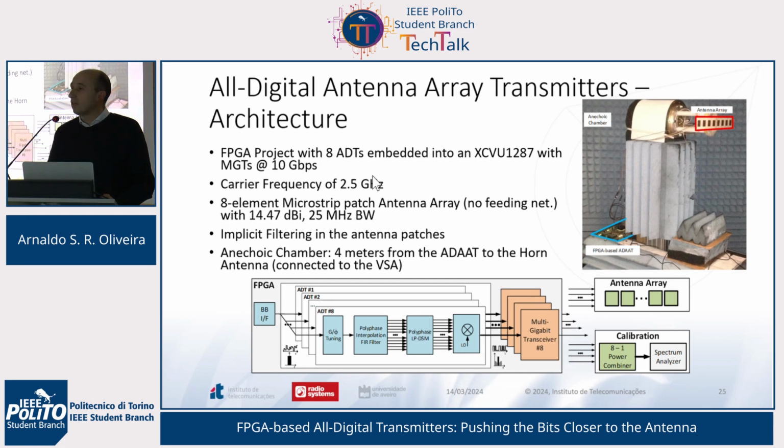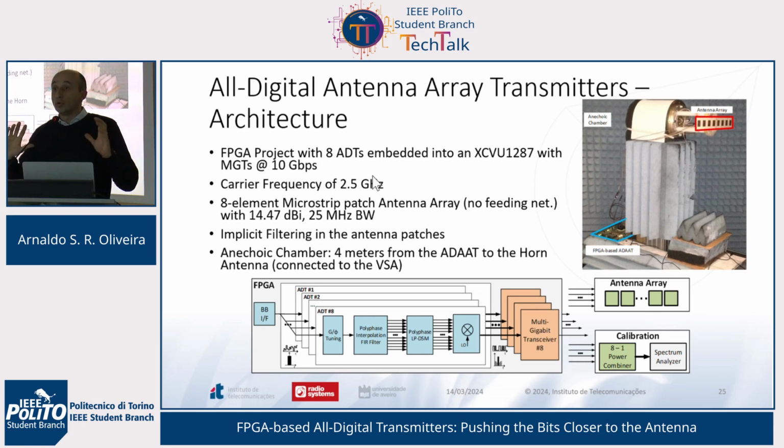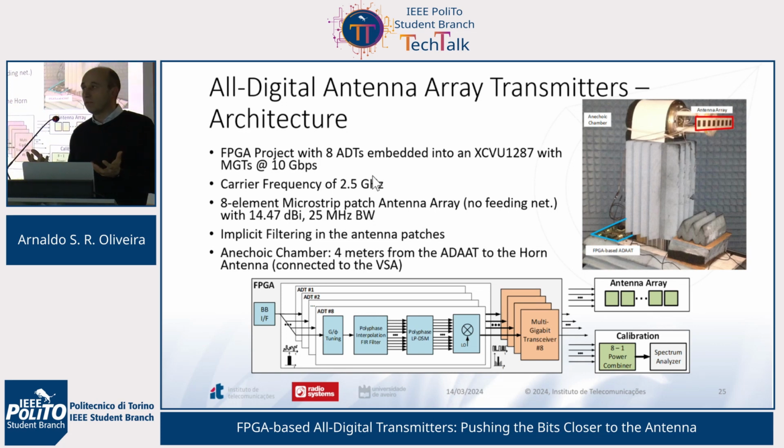Each transmitter itself follows a multi-phase approach, because in a digital transmitter we can have just a single phase, which means just a single path on the delta sigma, a single path on the PWM, a single path on the digital up conversion, or I can divide the circuit into multiple phases in order to allow parallel processing of each phase, to reach an equivalent sampling frequency higher than the clock rate at which I have to clock each phase individually.